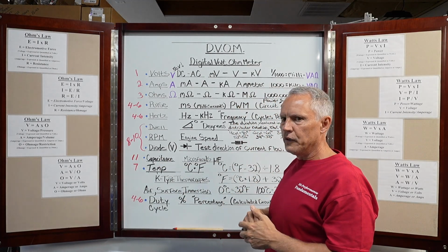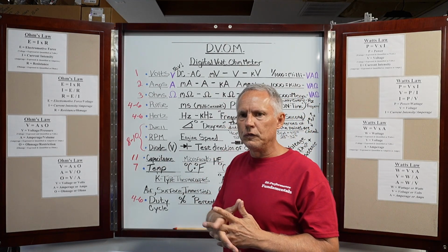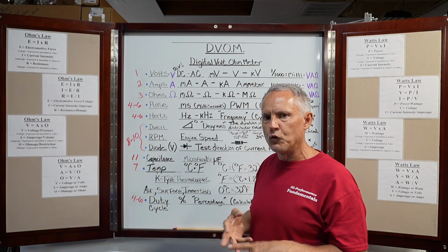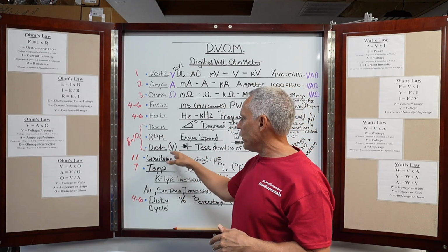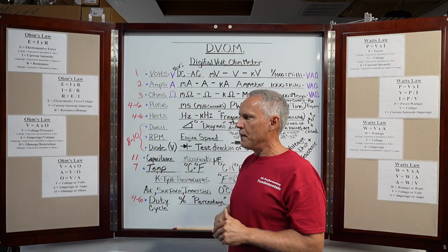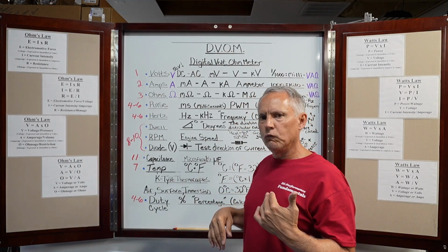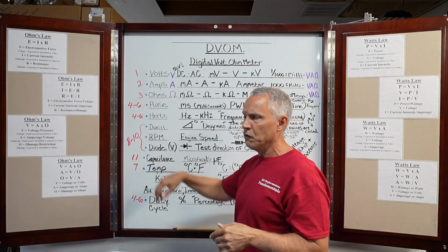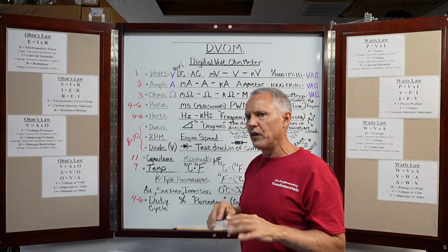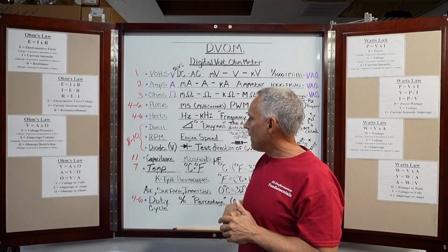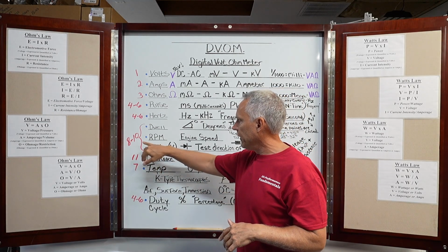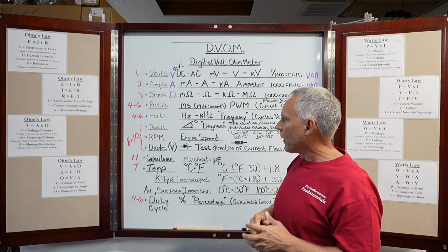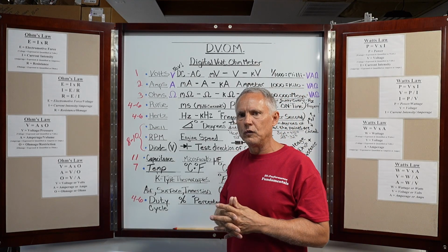For years and years and years, I used to rebuild alternators. And in an alternator, you're checking the rectifier bridge and the diode trio, or the triode. Used it all the time. Nowadays, when I'm wiring race cars, doing some creative circuitry, I'll use diodes. I'll put them in a system for different things, for circuit control. And for that function on the digital voltmeter, I do still use that quite a bit. Not like I used to. I don't really build alternators and all that like I used to.